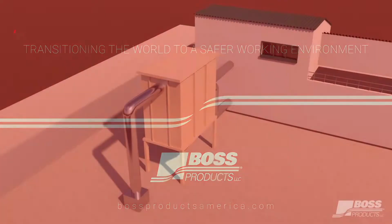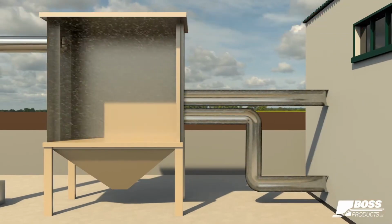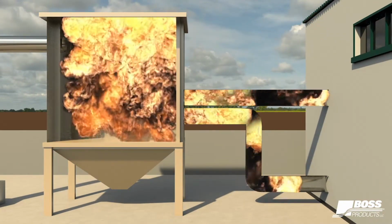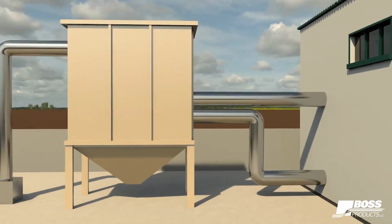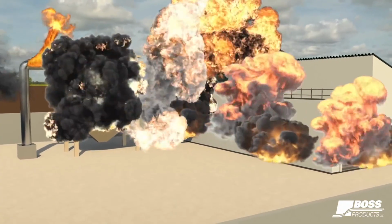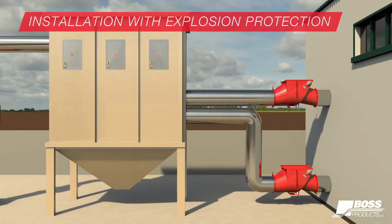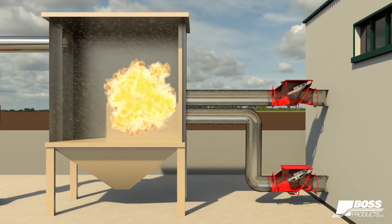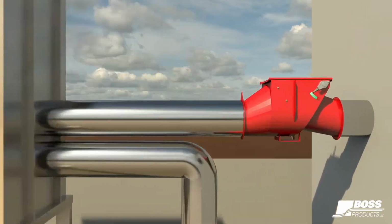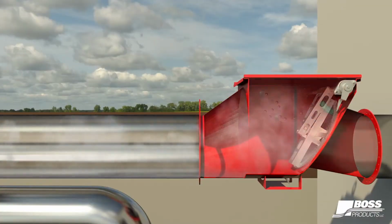Next slide, Andy. This is basically how we can configure our explosion isolation valves, our Vigi flaps. We can put Vigi flaps in a lot of different configurations. It's very versatile when it comes to how you can install them. As you can see, you can put it on the clean side, which would be the left side of that vessel it's protecting. And if you have two inlets, you can put multiple valves. You can have one on one inlet, one on another inlet. You can see that there's elbows in between that.